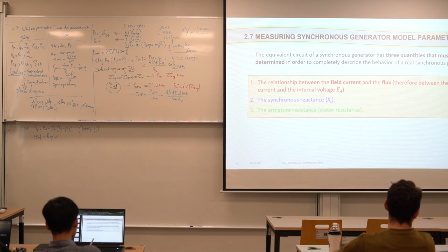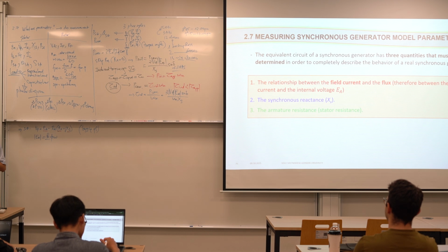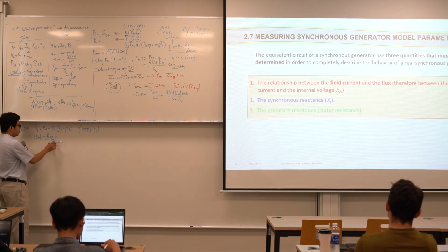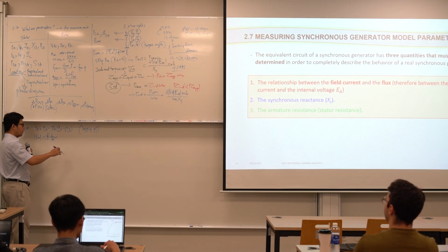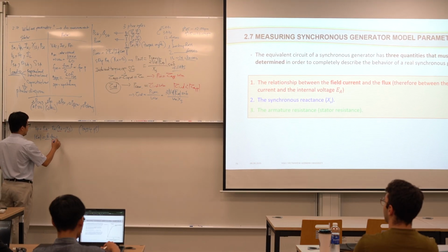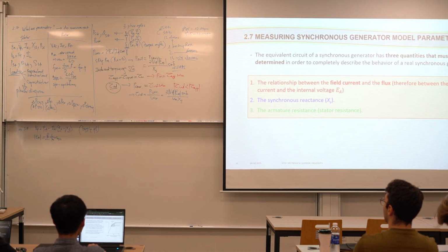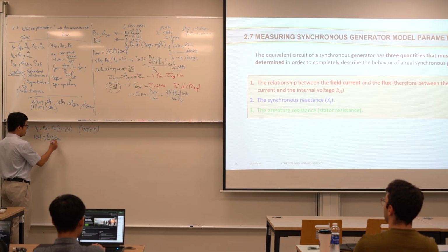Going back to Faraday's law we discussed in lecture 1, what does K mean? K is the mechanical construction factor. Omega here is omega m. Phi m is the rotor magnetic field across the air gap coming to the stator. And this is omega sync, the synchronous angular frequency. This is constant.